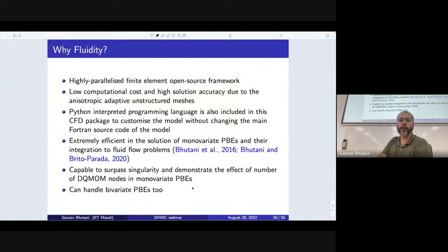Now in finite volume, the way we implement it, we have to find flux terms. If you have used it, you will see that if you want more accuracy, or if you change discretizations, you need different discretization for flux terms. So finding those flux discretizations can be very challenging and very particular to a given problem. But in FEM, it is very natural. With higher accuracy, you go from linear to quadratic, quadratic to cubic, and then you can increase accuracy.